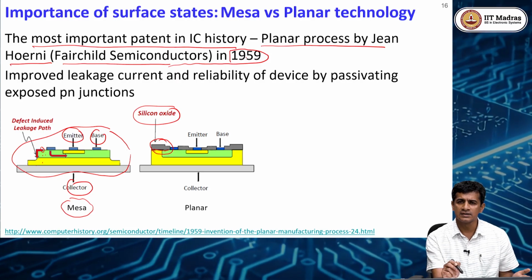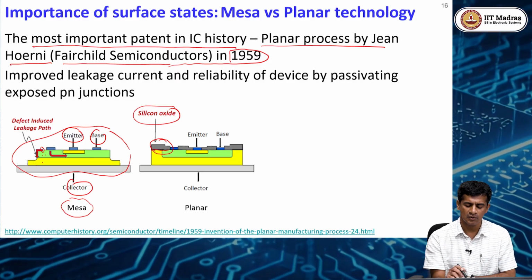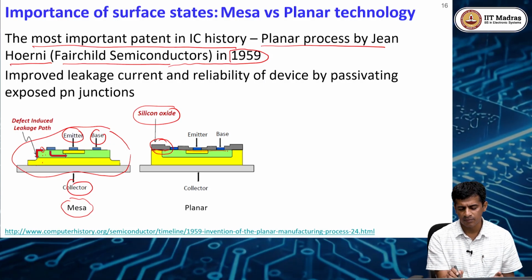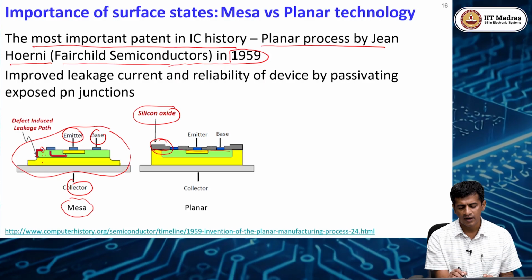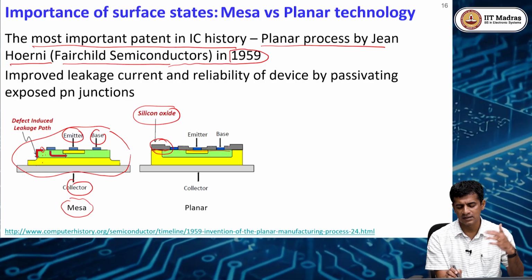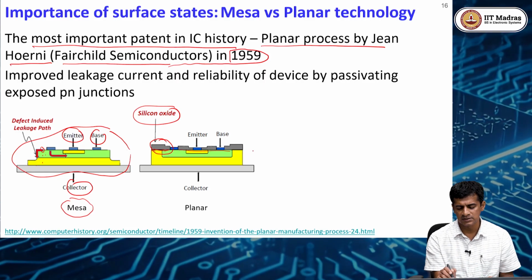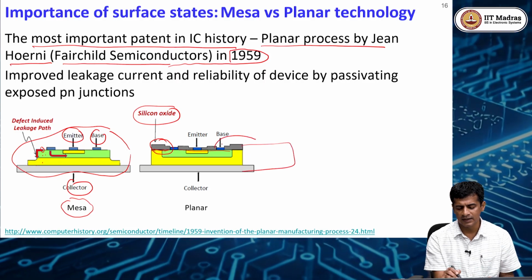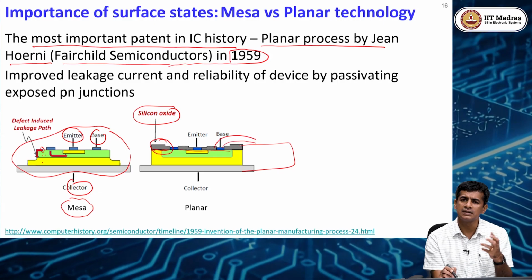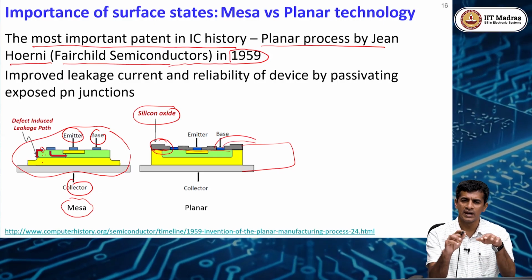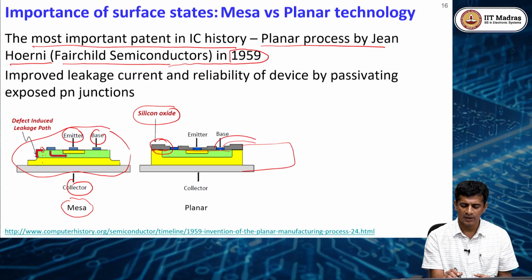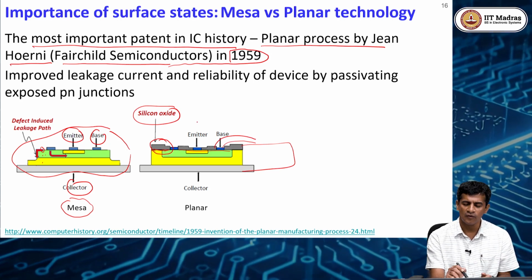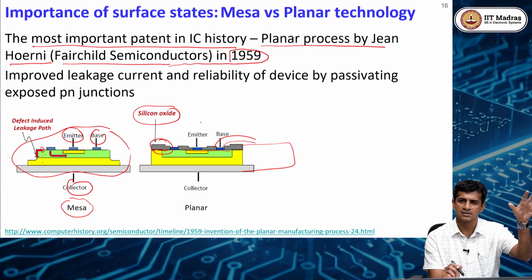The other important thing is that this is known as the planar process; the surface is planar. Now you have silicon dioxide sitting everywhere. Suppose you make another transistor here, then you can interconnect these two transistors by just depositing aluminum. You etch trenches in the oxide and you can interconnect them. So you can go from one transistor to many transistors.